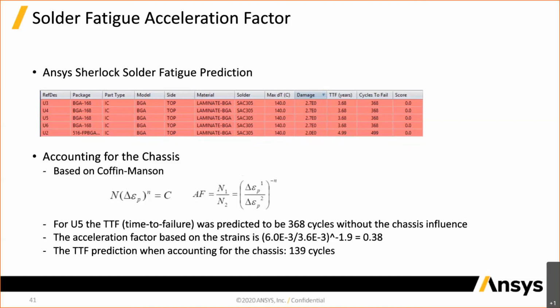You can also see it when you bond a PCB directly to a piece of aluminum for like a heat spreader. Sometimes people will have the metal in a certain area and free up some other area where there is no metal, and then all the strains just get focused right on that free area because that's the only place the board can relieve itself.